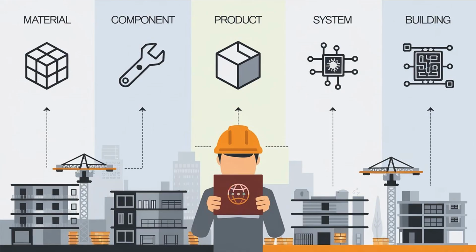Here are some key considerations about material passports. Different passport levels. There are a variety of passport levels, and the relevant stakeholders need to clarify which types of passport is required. As defined by Buildings as Materials Banks 2020, the hierarchy levels are material, component, product, system, and building. Not all materials are going to have a passport for every level listed, and therefore the information needed for each material and product may differ. Ideally, materials passports can be aggregated upwards to feed into building-level passports.